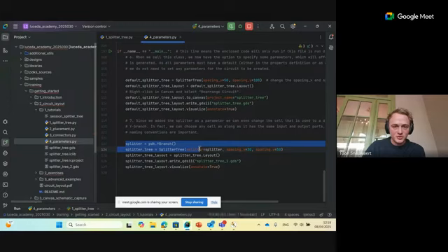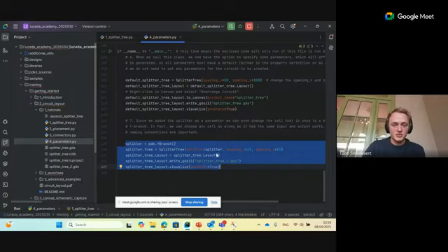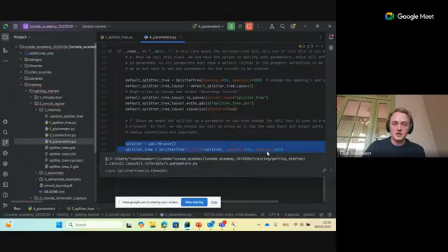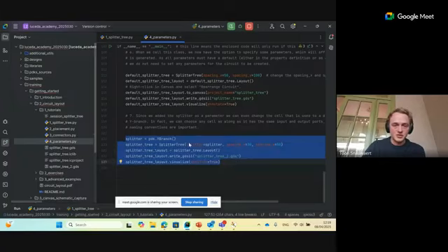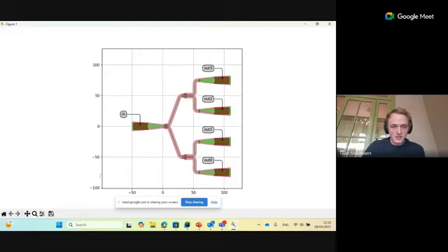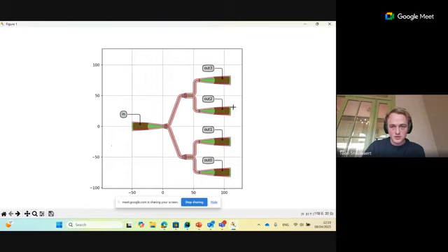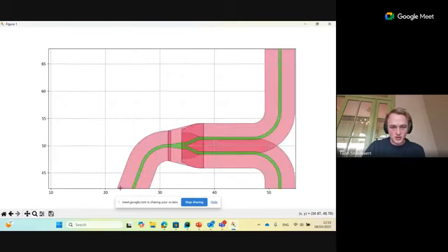Now we're at this part of the code where we select a different type of splitter, and we can use that inside our splitter parameter. So also the components we can change inside our circuit. Here we choose, instead of an MMI, a Y branch, and then we get this circuit, in which we can see a Y branch as splitting components everywhere.